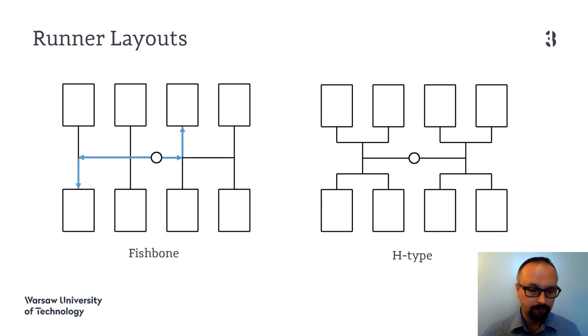The length is different. We can see clearly here that the length of the flow path to the first cavity is much shorter than the length of the flow path to the last cavity, and that's of course the reason of mold filling imbalance if we are not making any kind of so-called rheologically balanced runners, so without changing the diameters of the runners, of the gates, and so on.